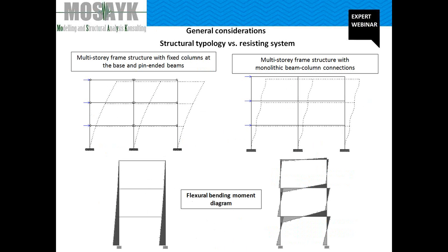Again, we can say that in a precast structure, the characteristics of the connection, which are strength, stiffness, ductility, energy dissipation capacity, post-yielding stress degradation, and more, between the structural elements determine the global response of the building. Let us try to demonstrate this by considering two frames.